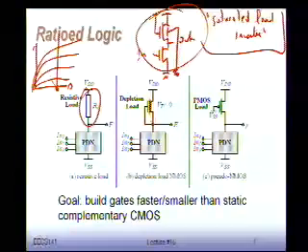A depletion transistor is an NMOS transistor with a negative threshold, which you can do by doing some implants. I can move the thresholds up and down. So you can see that this acts as a current element, and actually was a fairly good load until, as I said, in the early 80s when CMOS came in.